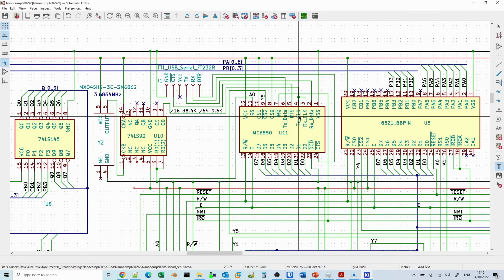And then we see here that the transmit clock and receive clock both can be tied together and driven from the same clock signal. Some very low baud rate equipment sometimes had a different baud rate. Teletypes had, I think, 110 baud for output and a lower baud rate for input, 75 baud, I think, for input. It was something like that. The transmit and the receive clocks are going to be identical here.